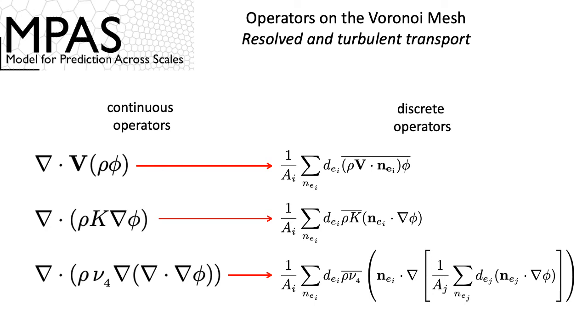If you look at what that means in terms of discrete operators, this is the discrete operator we looked at previously. This is the discrete operator for the turbulent flux, the second order turbulent flux. Here is our turbulent velocity, our density times the eddy diffusivity. That's what these two terms are, times the gradient of the mixing ratio. That's a traditional turbulent flux formulation in a finite volume form.